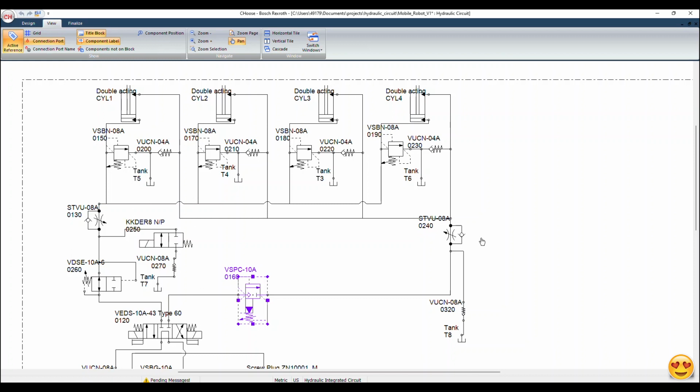From the other side, we have the opposite side at the right, as you see. When the pressure changes and the flow path changes, and the platform is sitting down, it is also important that the platform does not drop. So we also need a speed regulator with this restrictor, or needle restrictors, to control the flow rate.